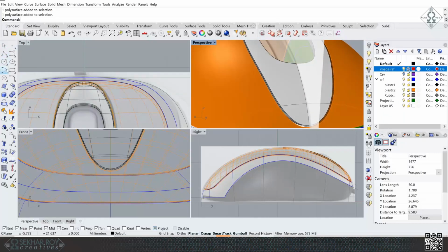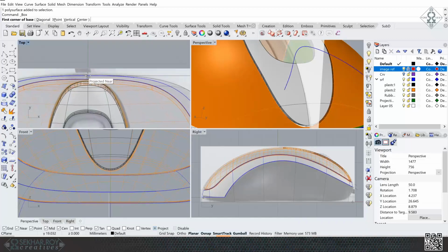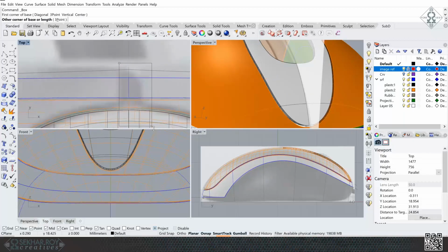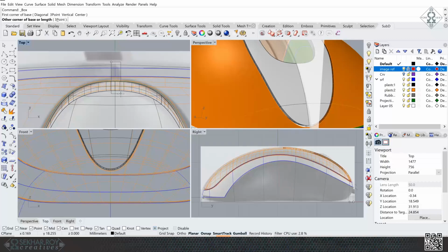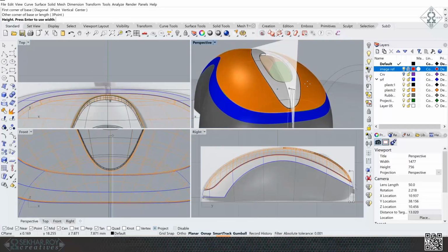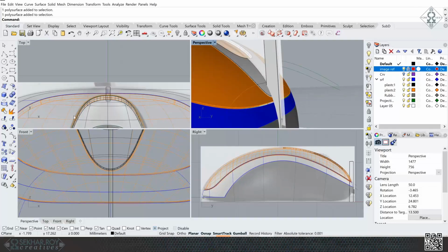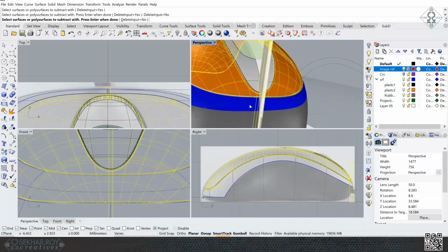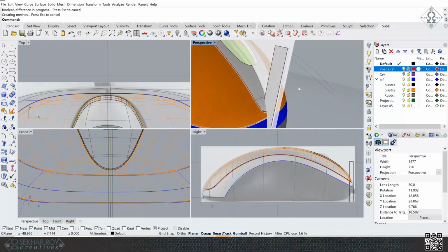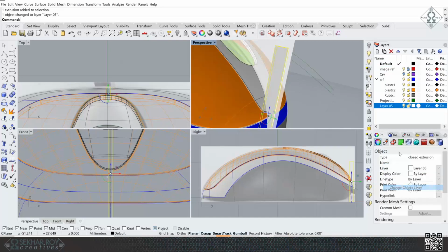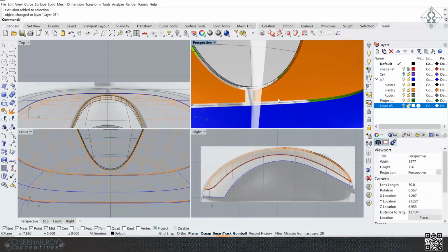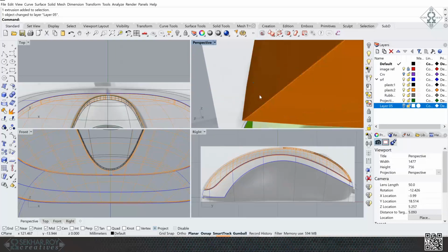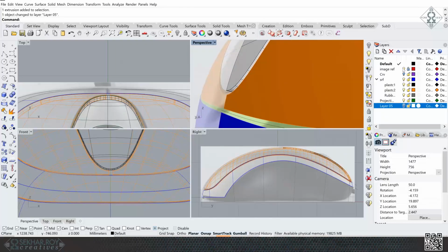Okay, and so I'm going to go here a quick box, and using the image reference, so let's say the box is about this much. I'm going to raise this high. Boolean difference. I want to cut this object, enter, using this box, delete input to no. Maybe I needed this to remove this also. So once I do that, let's put this in a layer and hide this. So it has created that gap for us, which is also a solid geometry, right? Turn off my image reference.